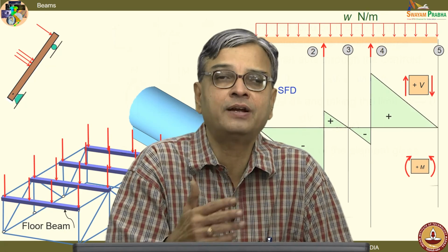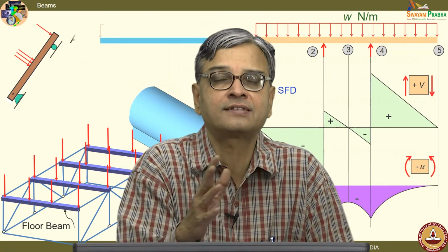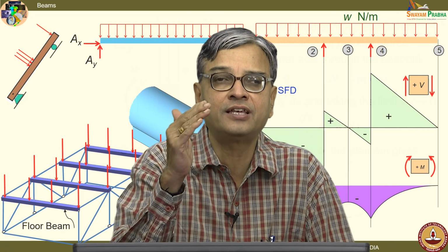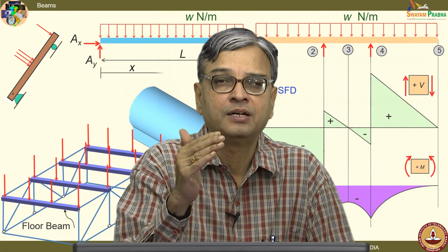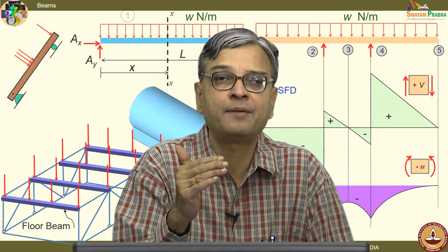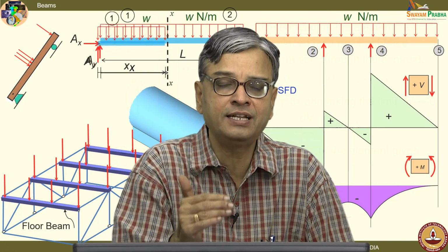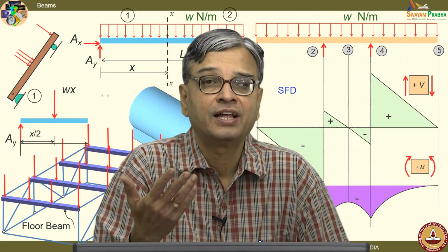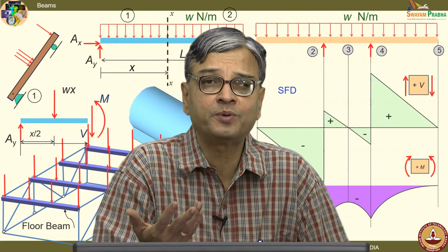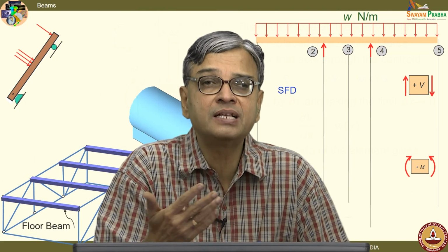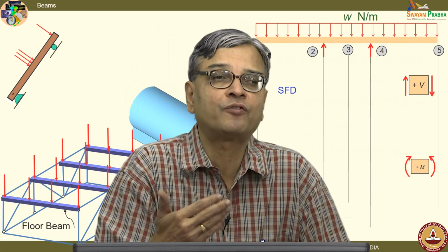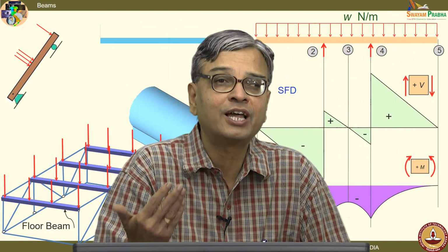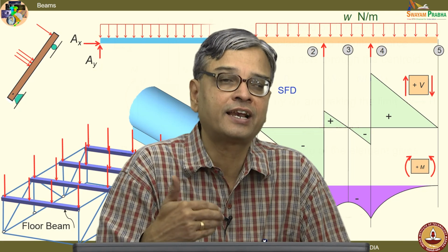And I have always recommended you must plan your answer script as well as your notes, so that you always write the loading diagram, shear force diagram and bending moment diagram one below the other. Its utility you will find for difficult problems where you may miss the plotting of the bending moment diagram, may be difficult, where you can take advantage of this interrelationship.